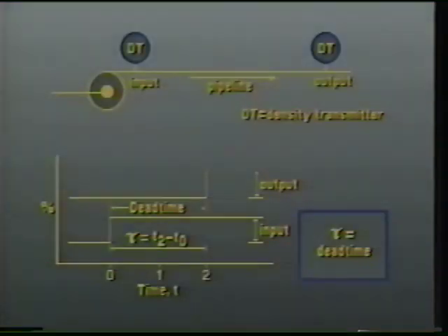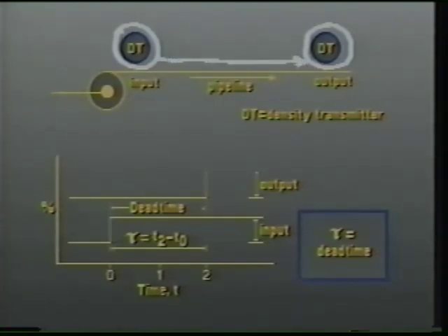For instance, consider a process involving laminar flow through a pipeline in which the fluid enters the pipeline here at a certain density as monitored by an input density transmitter. Another density transmitter is positioned at the output downstream. Assuming that both transmitters have the same measurement span, we should be able to measure the time between the change in fluid density at the input and the corresponding change in density at the output.